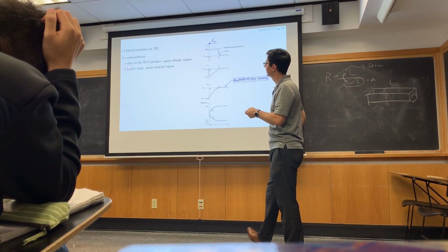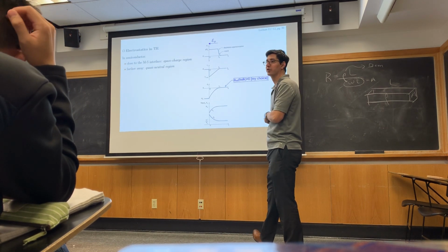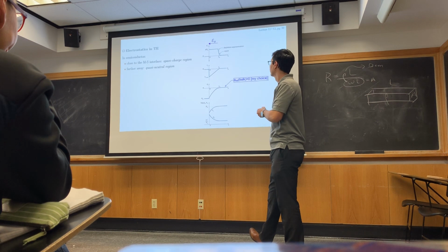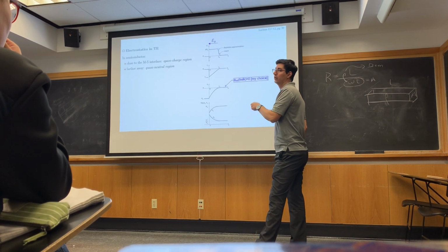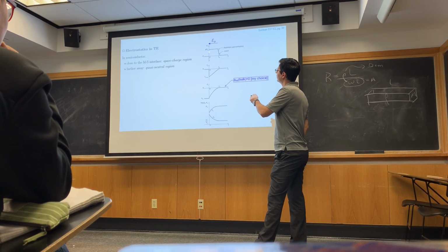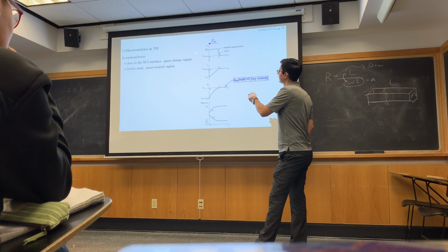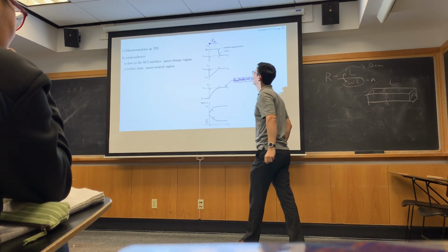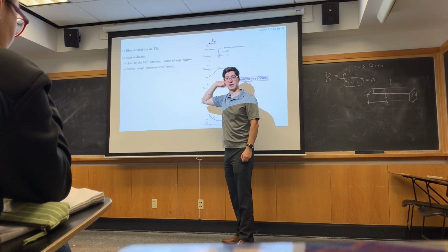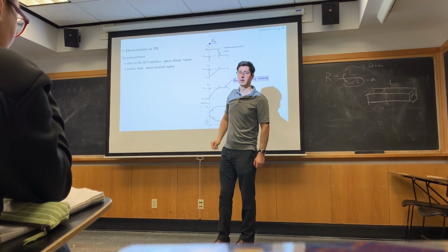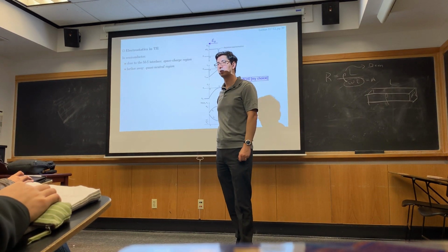So let me just say these things. Close to the metal semiconductor interface, I'm going to have a space charge region. Then further away, I have a quasi-neutral region. Okay? So here's my picture of rho. I'm going to do the depletion approximation again. Now this time, the charge on the metal is basically a delta function. It's not exactly a delta function, it's some distribution with the width of the Debye length of the metal, which is less than a nanometer.